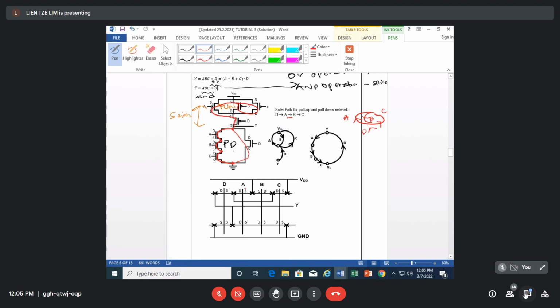So you see here the source terminal. How to determine the source and drain terminal in the stick diagram? Here you see the connection with the contact to VDD, and here the terminal is labeled as the source terminal. It is best that we minimize the number of connections. If we can make them one similar terminal, that is, to the VDD, then we should make it that way.